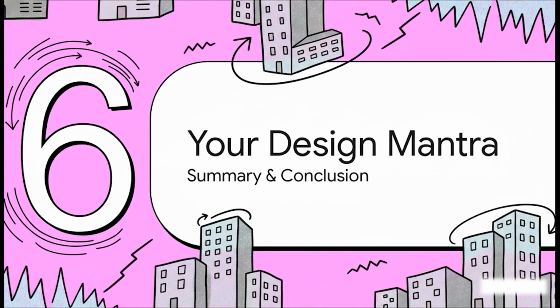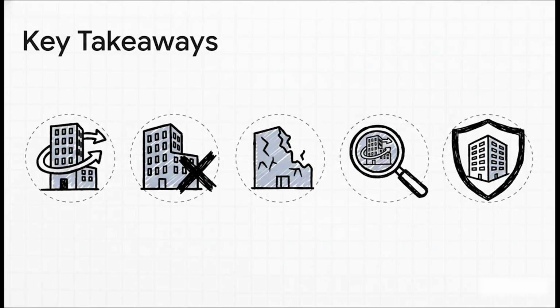Okay, so let's bring this all home. What's the ultimate takeaway for anyone designing buildings in a place where earthquakes are a real threat? If you remember anything from all of this, remember these points. Earthquakes make buildings twist. Asymmetry, in weight or in stiffness, is the enemy. The real-world consequences are life and death. You absolutely must design for an amplified twist, not just the one you calculate. And above all else, symmetry in your design is the most powerful weapon you have to create a safe building.